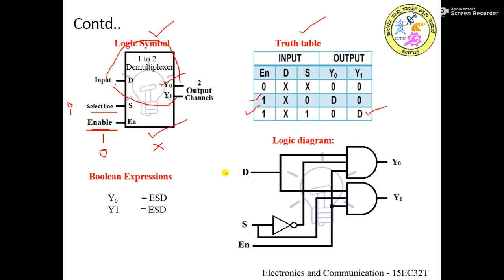Next we shall write the boolean expressions for the outputs. Since there are two outputs, we are supposed to write two boolean expressions, one for y0 and one for y1. It is very simple. Here we need not draw any K-map or do any simplification. Simply, for the combinations where the output is not 0, we take the corresponding input combinations and just multiply the literals.